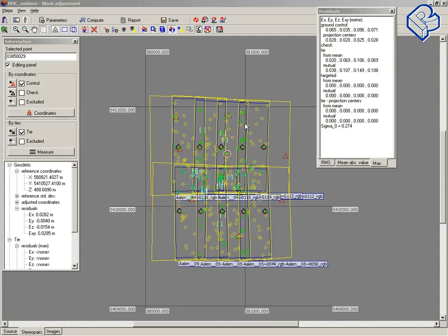How do you find the basis value? Actually, Sasha has shown the way to just compare two x coordinates for the right image and left image, subtract one from the other and get the basis. But in fact, you can calculate it easily if you know the overlap area between two images. You can easily calculate the distance between the centers of images in millimeters, pixels or meters if you know the approximate scale.